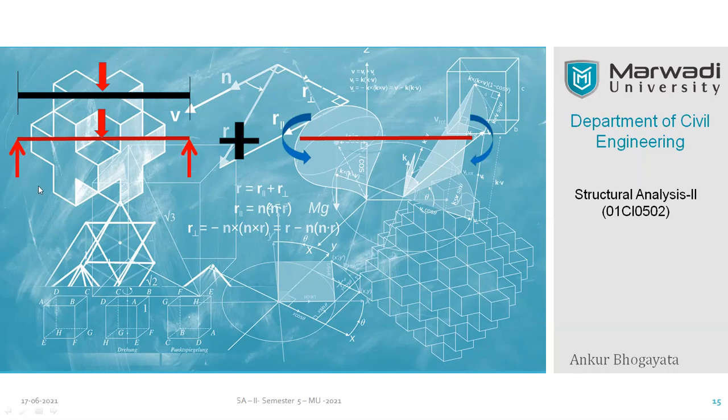Yes, you know that it's going to be a triangle, right? And here in this case, again my life is very simple so that I can apply the unit value of the moment. So for me, the diagram for this structure will be nothing more than a rectangle, because at both ends I have equal moments, right? So my diagram will be nothing but a rectangle over here, as you know from the earlier concepts.